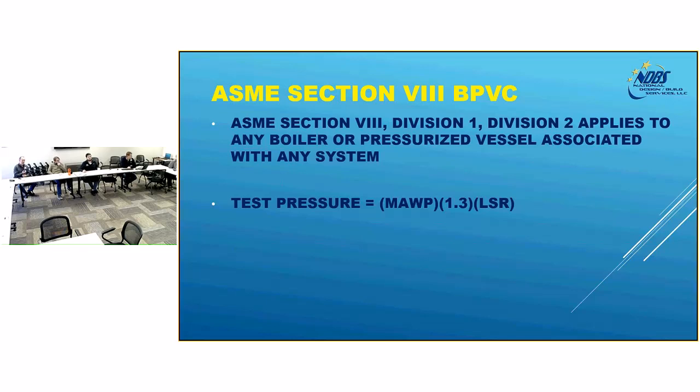They did a vessel inspection. A company was asked to put in a patch plate on that vessel. They filed the R1 for the use stamp to keep the vessel legal, but they advised the owner that they have several spots that are thinning out, and they, in writing, advised that that vessel be replaced at the earliest. And unfortunately, the owner did not want that expense. The boiler operator in charge of that boiler system also died during that event. So pressure vessels are kind of a big deal.